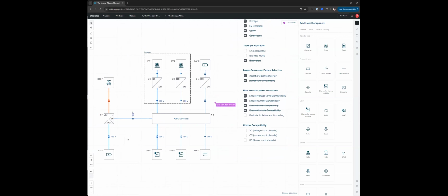That's right. So when we look at converter one, converter two, we'll make sure electrically it works, and do they have the control modes? Because once those two things are in place, then with a microgrid controller, you can make sure that you can orchestrate at least their operation. Now, there's a lot more things that go into dynamic and steady state stability, but on a high level,